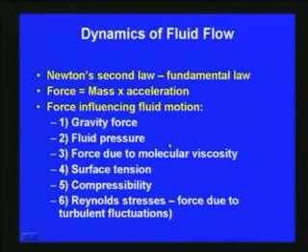So the second force influencing the fluid motion is the fluid pressure, and third is the force due to the molecular viscosity within the fluid itself. The fourth one is the surface tension, which acts upon the fluid surface. So surface tension is important, and then whether the fluid is compressible or incompressible. The compressibility of the fluid affects the compressible force that we have to consider as far as the fluid motion is concerned. And then lastly the Reynolds stresses, that means forces due to the turbulent fluctuations.